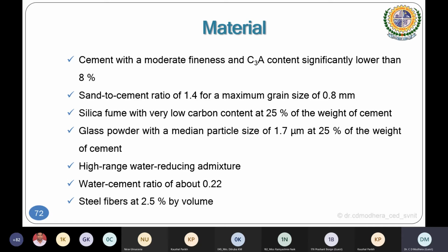See, each point involves so many hypotheses, so much research has been implemented, under certain ideal conditions. Remember this: if you take the same and prepare the mix, and the environment is the same, then definitely it can be manufactured, but it is not happening at all. When you are calculating on a piece of paper and providing a mix proportion, sometimes you will not get a good cohesive mix, and sometimes workability may be an issue.